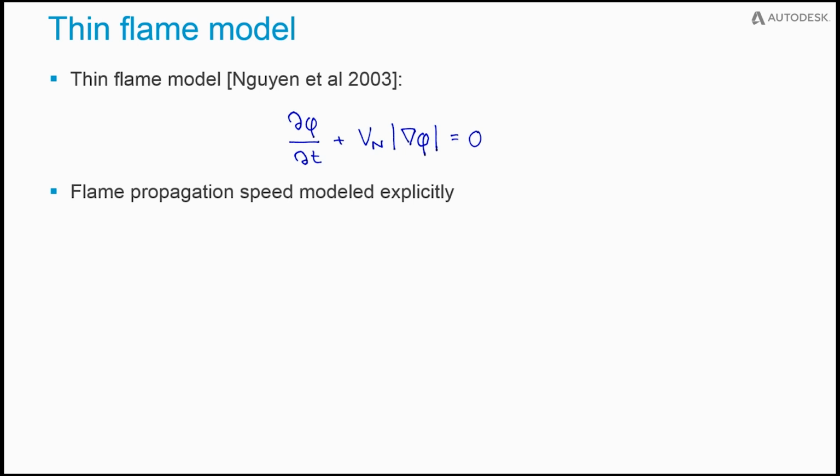But what we found, and what is consistent with the approaches taken in CFD, is that if you really want to model this accurately and get the correct flame propagation speeds throughout your fuel, you need to take very small time steps, and you need to also model all these intermediate reactions that we're not really interested in if we can get away with it.